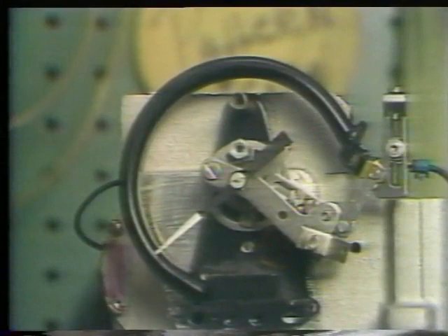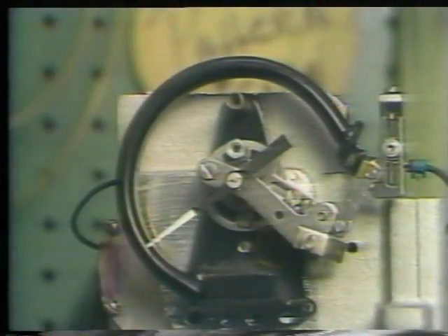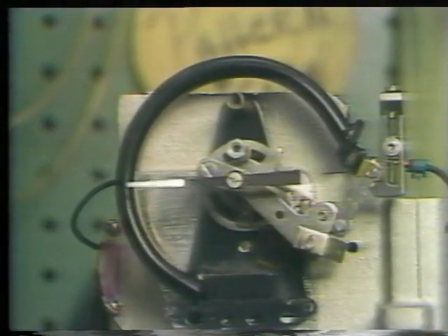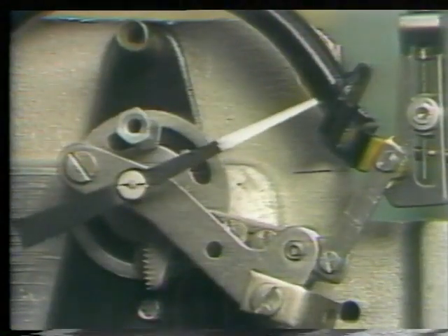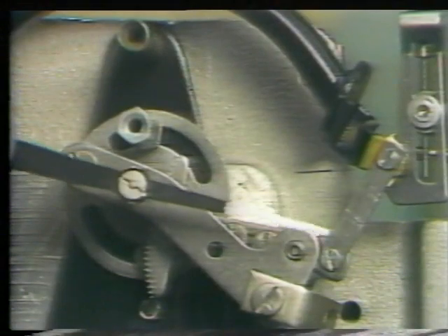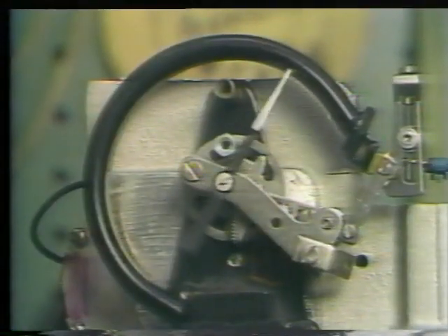Inside a Bourdon tube gauge is a curved tube that is sealed at one end. When pressure is applied to the tube, it attempts to straighten the tube out. The greater the pressure, the more the tube tries to straighten. The movement of the tube is transferred to the pointer on the gauge by mechanical linkage. When pressure decreases, the tube returns to its original shape. All Bourdon tubes work on this principle of trying to straighten out a curved tube.